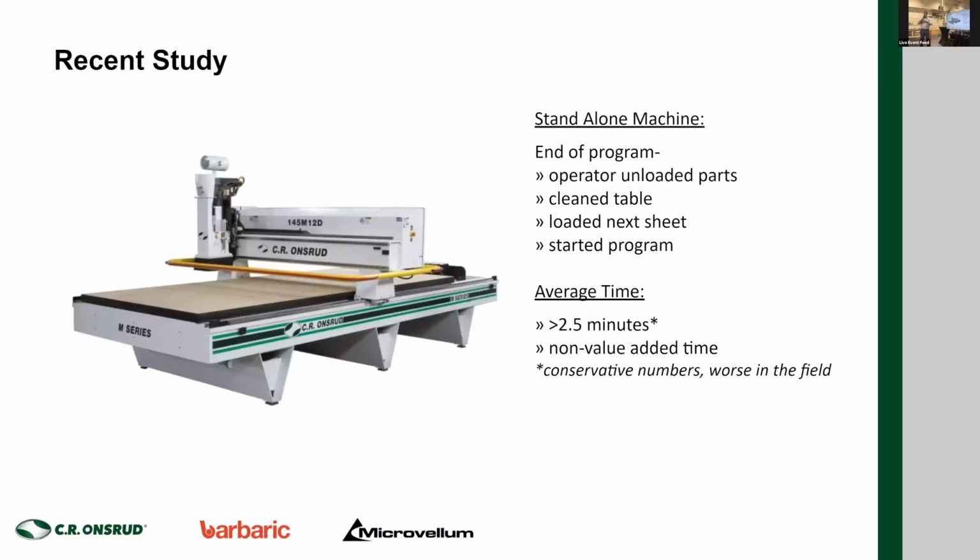So talking about that non-value added time, we recently did a study on one of our smaller entry-level machines, and at the end of the program, when the machine was done cutting, we started the timer and timed from when the operator unloaded all the parts, unloaded all the scrap, cleaned off the table, loaded the next sheet, and then hit cycle start on that program.